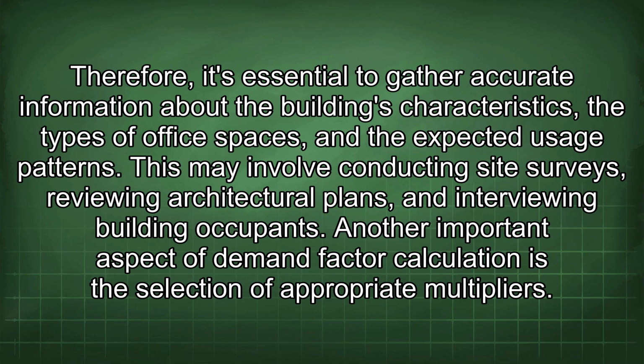Therefore, it's essential to gather accurate information about the building's characteristics, the types of office spaces, and the expected usage patterns. This may involve conducting site surveys, reviewing architectural plans, and interviewing building occupants. Another important aspect of demand factor calculation is the selection of appropriate multipliers.